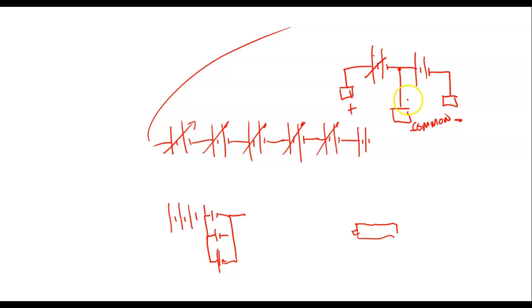What I'm not doing is using the common. We should get about 15 volts right here, 15 volts right here. They're in series, so I'm not using this. I'm bringing it in here, coming out here, and going to the next one. That means each power supply should give me around 30 volts, and I've got 6 of them. So what should we get? We should be able to get around 180 volts out of these things, right?